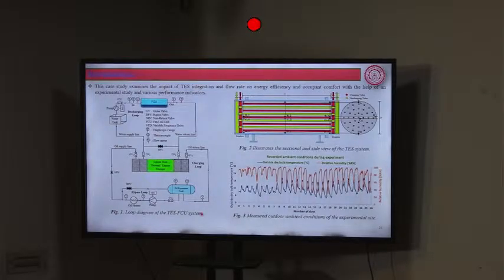Solar salt, of course, has sodium, but we also had the other two, which are nitrates and nitrites. And then one more system we have introduced in this thermal energy storage system, which is the cascaded system. A cascaded system is nothing but a series of phase change materials arranged in a way that the melting point of one helps trigger the melting of the next. Once the entire first chunk of salt gets melted, it will transfer the heat to the next chunk of salt.